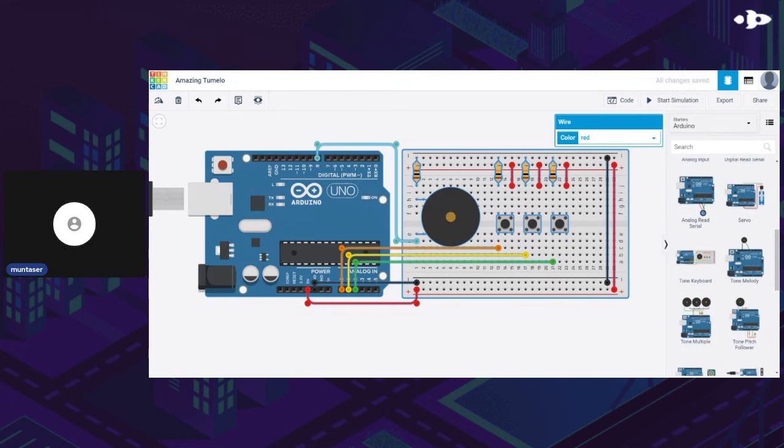So it must finish a loop. And in order to finish a loop, you need to have a ground and a power line. The power line connects to one of the rails, and the ground line connects to the other rail. You can extend these two by looping together with a wire this rail to the other black rail, and the red rail to the bottom red rail. Now, everything that's on this is ground. Everything that's connected to this is power.